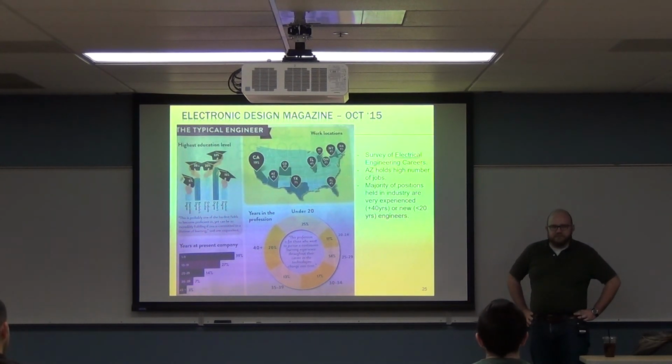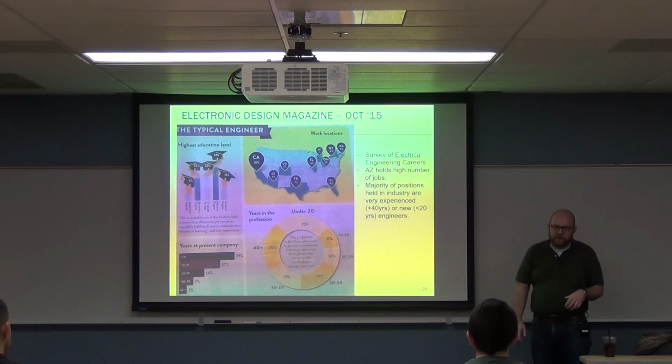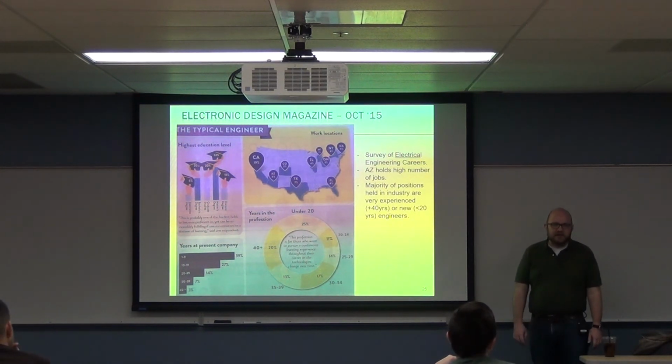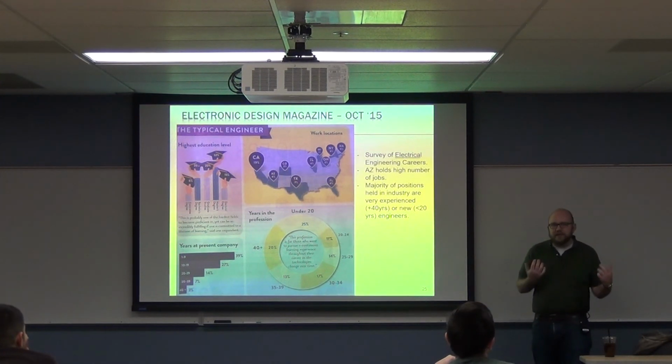So you aren't writing the language that implies this. You aren't writing a language that gets translated into the circuit. You're more or less writing an HSPICE netlist in a very strange way. That's sort of how I got into it. I went, oh, okay, when I want this module, I'm actually placing this module. When I want an AND gate, I'm actually placing this AND gate. From my perspective, that's how I realized it was circuit design for me, because that was the input medium. And it was actually a lot faster than drawing schematics, because I can type very fast. That worked well for me.